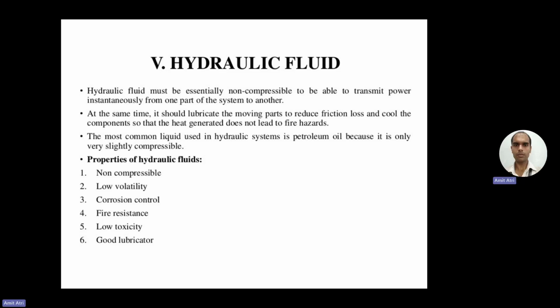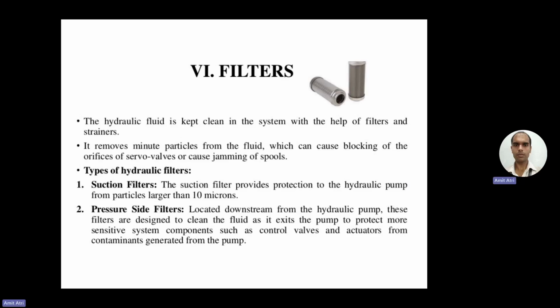So the most common liquid used in hydraulic system is petroleum oil because it is only very slightly compressible. So properties of hydraulic fluids like non-compressible, then low volatility, corrosion control, fire resistance, low toxicity, and good lubricator.